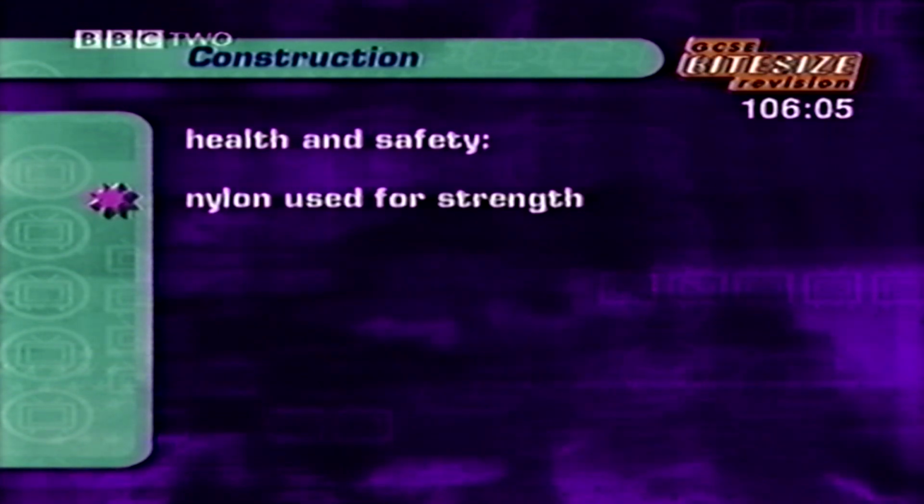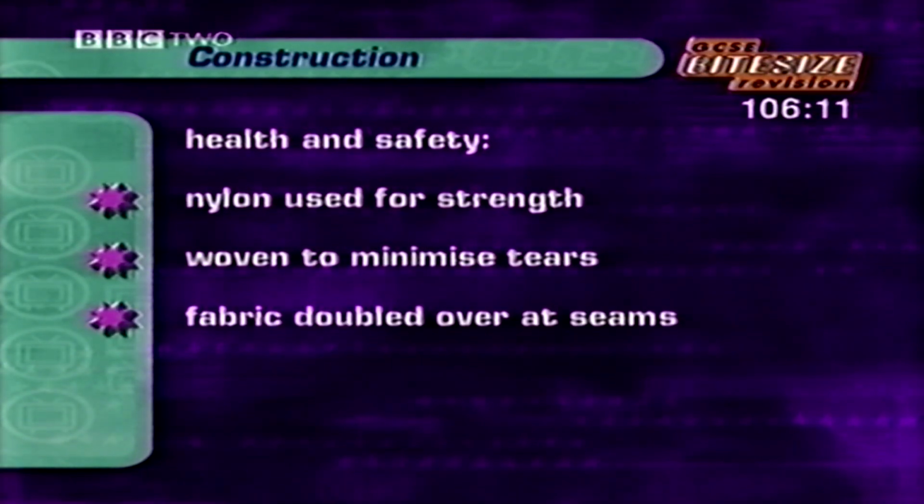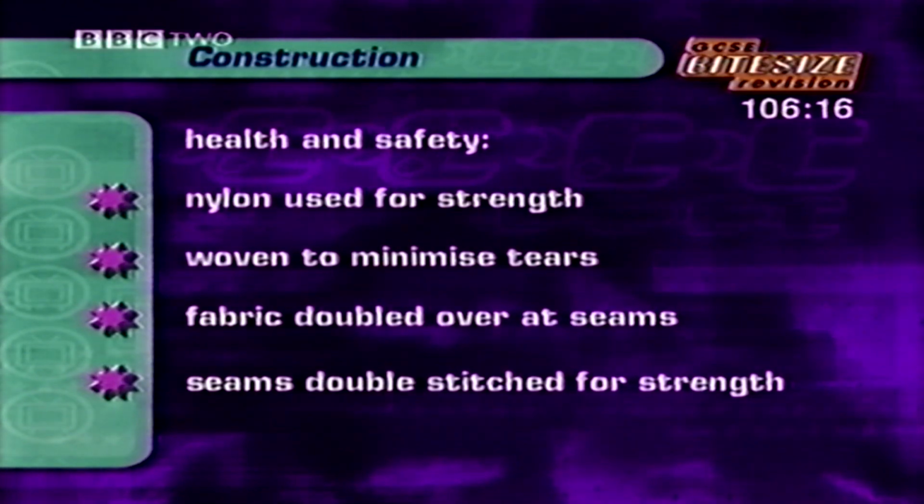Crucial consideration was health and safety, since hot air balloons must meet the same safety standards as jet airplanes. Nylon was used for its strength and durability. The way it was woven ensured that tears were kept to a minimum. Seams were stitched with the fabric doubled over for strength, and the seams themselves were then double stitched.